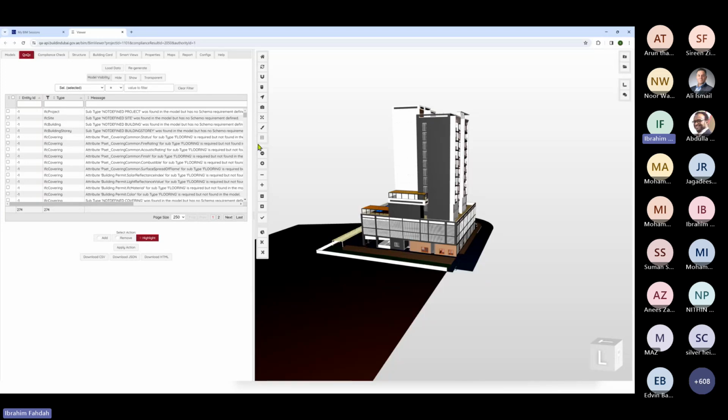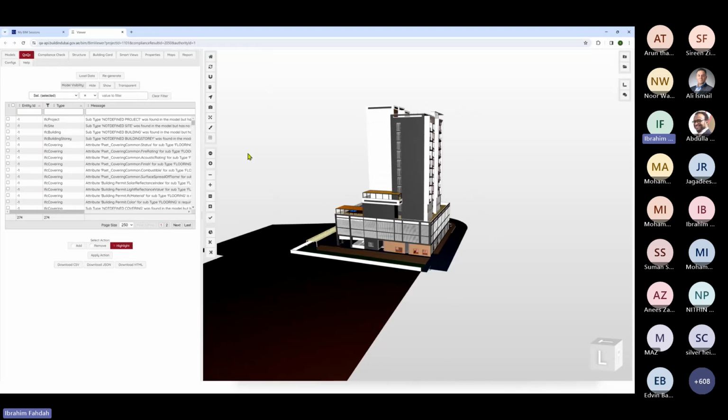What you should do in this case is not submit this model, unless, of course, it's preliminary or for another reason DM might accept this. But typically you should go back to the BIM authoring tools and rectify the issues and the information, go back again and upload a new version of the zip file, and make sure it's all clear that there are no QA/QC issues.